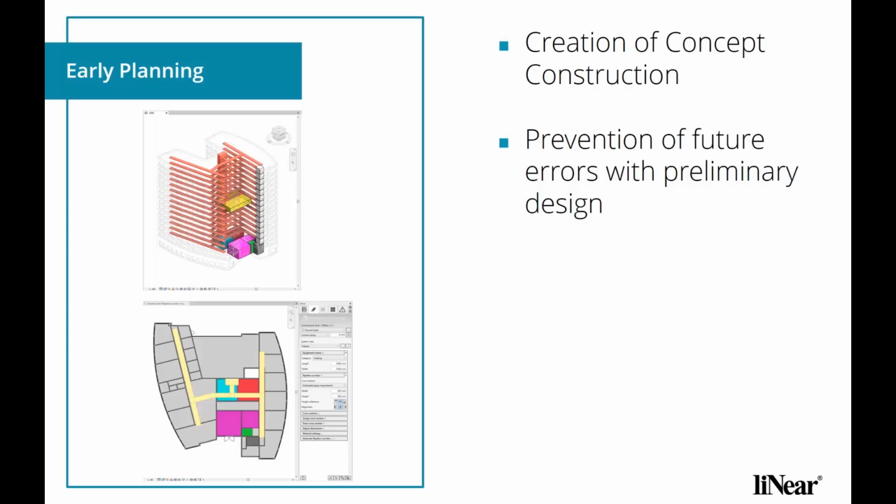The pipes of the individual trades run from the equipment rooms to the consumers along pipeline corridors. With the pipeline corridor function, these can be constructed very easily. Subsequently, the cross sections are defined and assigned to the individual pipeline corridor sections. Adjust dimensions is a quick and easy way to adapt the space requirements of the pipeline corridors to the assigned cross sections. Once the pipeline corridor concept has been coordinated with all parties involved using IFC, the pipelines can be generated automatically and used as the basis for further design phases.